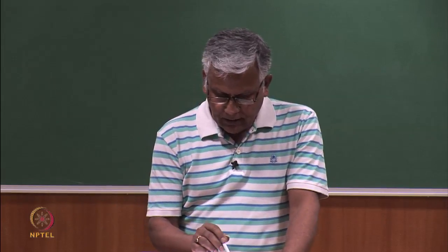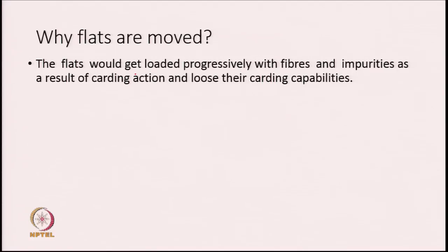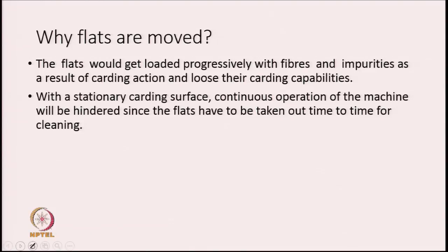The reasons are, the flats would get loaded progressively with fibers and impurities as a result of carding action, and therefore, after some time they will lose their opening capability or carding capability. With a stationary carding surface, if the operation is continued, it will be hindered, since flats have to be taken out from time to time for cleaning.